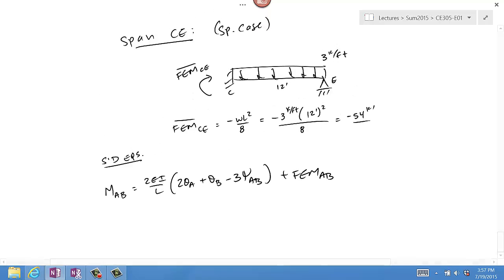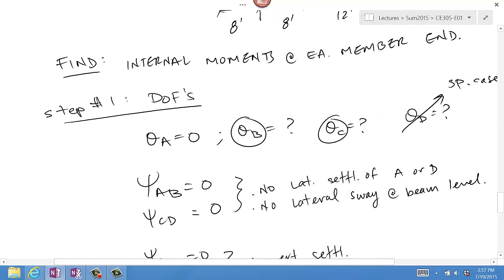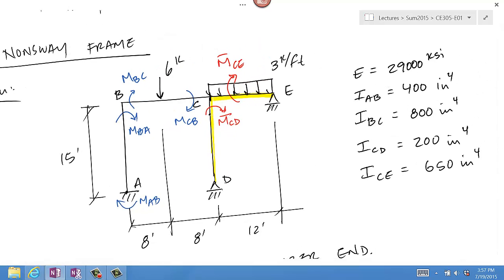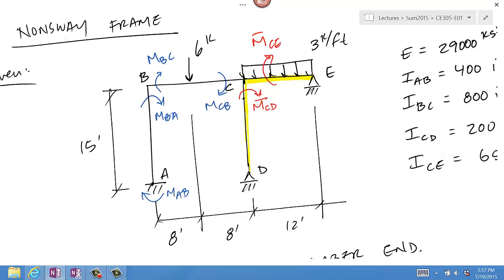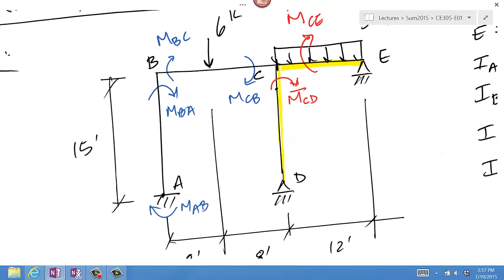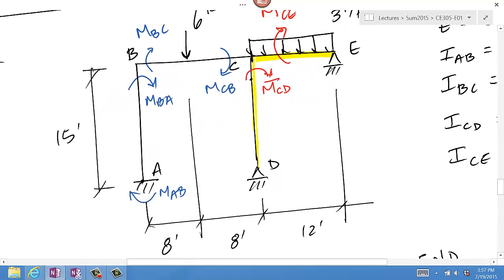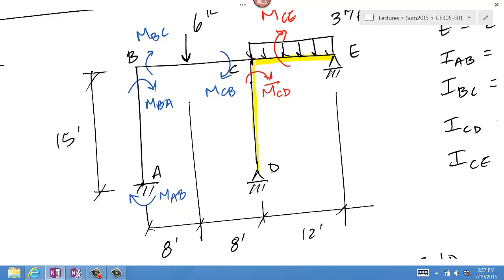Incidentally, this problem does give you different moments of inertia. But let's say that this problem was formulated a little bit differently. Let's say that column AB had 2EI and beam BC had EI. The point that I'm trying to make is that the 2EI would replace the quantity EI in the slope deflection equations.